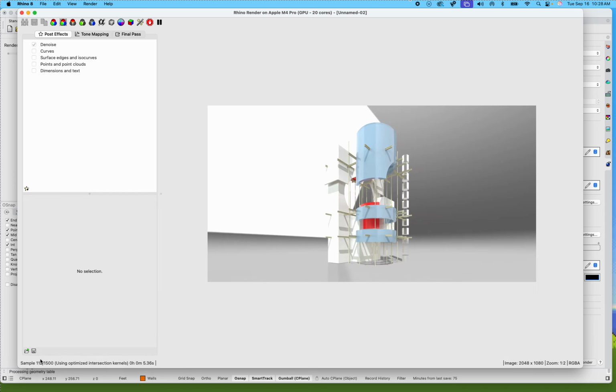Now you'll notice in the bottom left-hand corner, it's actually putting together a bunch of multiple shots, right? And the reason why it needs that is because, in order to get a high quality render, it needs multiple pieces. When we take a screenshot of our screen, it's going to the DPI of the screen. Now, if you have a Macintosh, it's usually a pretty good DPI. However, most Windows DPIs is actually kind of a faux DPI. It's really about 150 DPI, or sometimes even worse, 72 DPI, which is just awful quality.